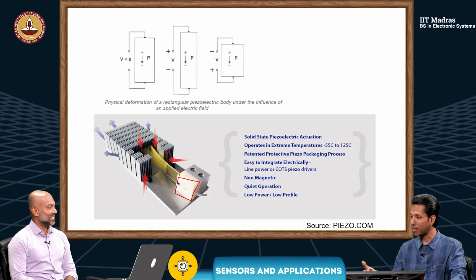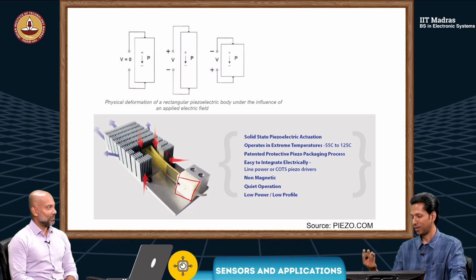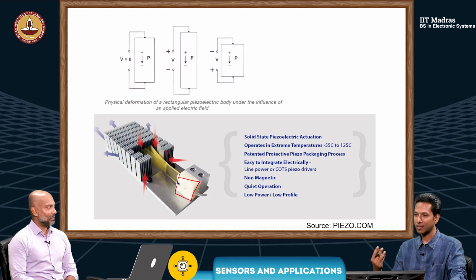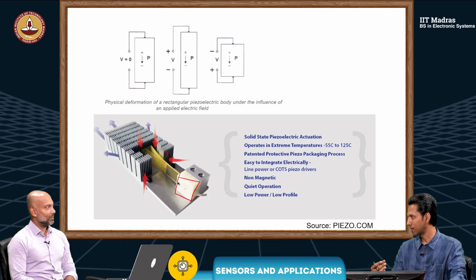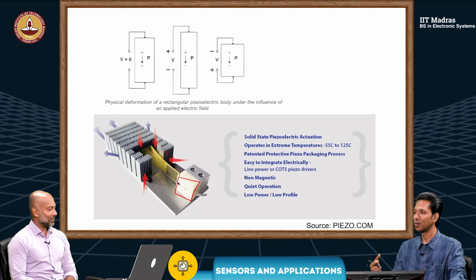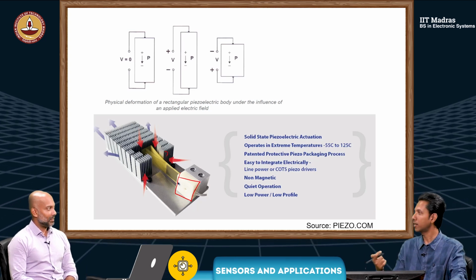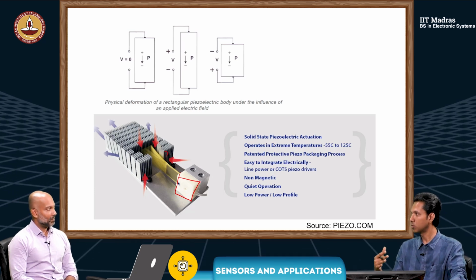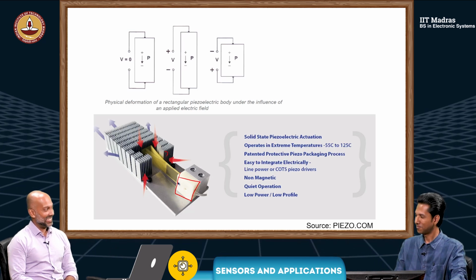Even if you use a battery, it may not be available forever. It works for some time, then you have to replace it. If it's not an easily accessible location, you cannot go and change the battery all the time. So it's good to look at the ways in which you can scavenge energy from the ambient, even sunlight. Piezo is one of the ways where you can get vibration to energy conversion.